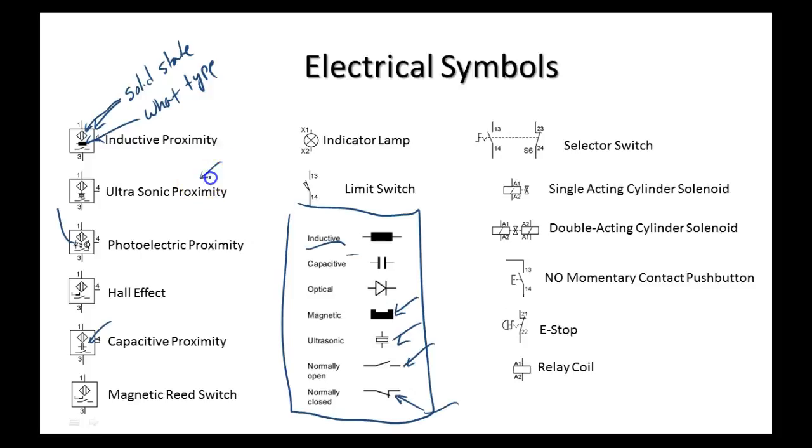Ultrasonic sensor is going to be used to sense distance, right? We can use it as a presence sensor, but this guy here is sensing difference. Probably a level or height, so in our situation, it's sensing height. So it's seeing if the part is what? Too small, or if the part is too big. But we can use these for a lot.